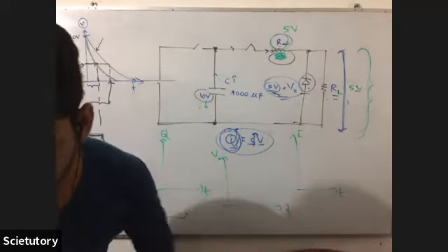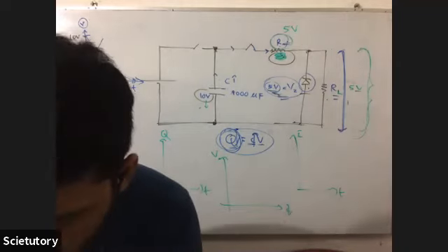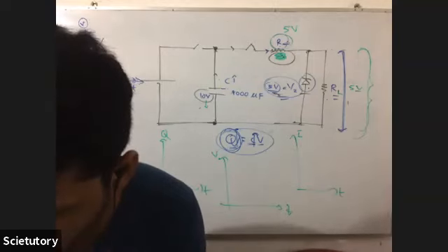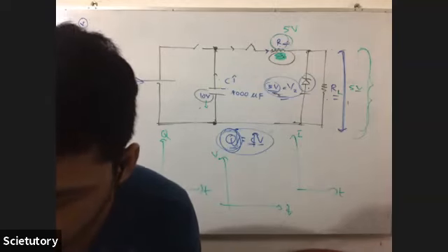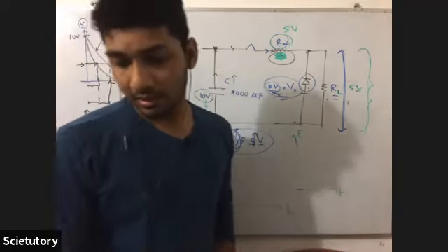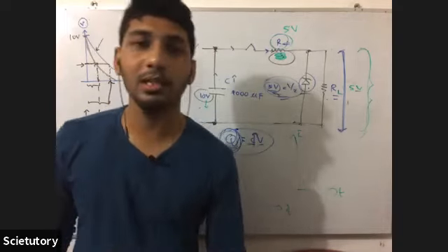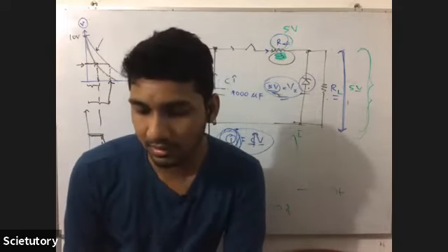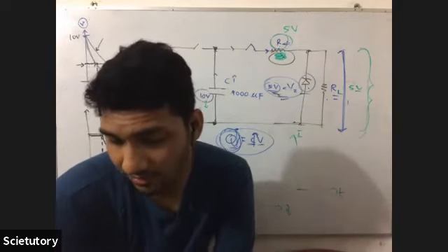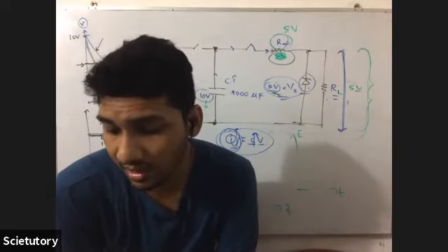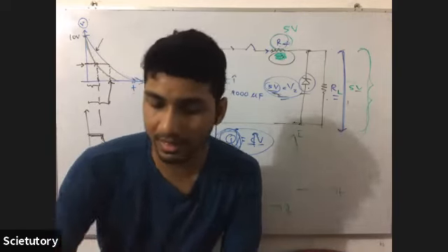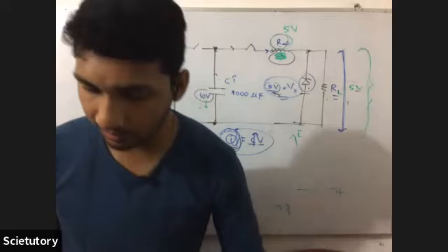Question 33. A and B shown below represent logical inputs applied to circuits 1 to 5 given below, and F represents the expected output from the circuit. So now, when you see this, you can straight away come to an answer. It doesn't deserve to be the 33rd question. So what's the answer? AND gate. You see, only when A and B are 1, the output is 1. At other instances, the output is 0. So this should be an AND gate.